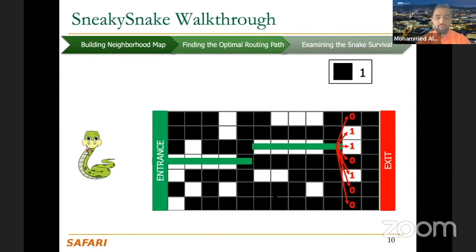Now, some of you could say, how come it doesn't matter? Because if I choose one far from this path, I'm going to use a vertical path as well, and that is a cost for the silicon or for the metal layer in the VLSI chip, right? Because we have multiple layers stacked on top of each other, to have vertical and horizontal lines or connections, and then connecting these layers far from each other might give you some cost, right? Because you are going to occupy this entire vertical connection over there.